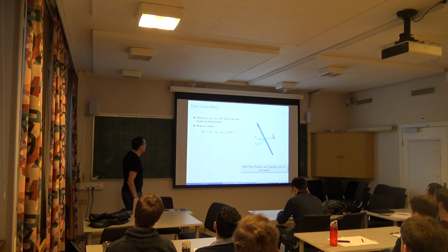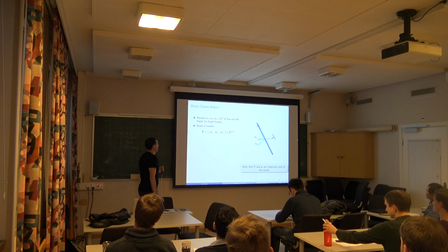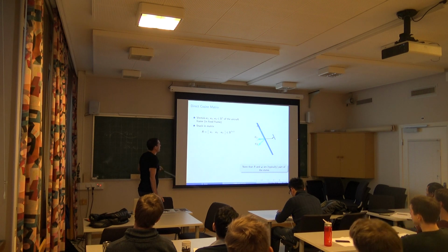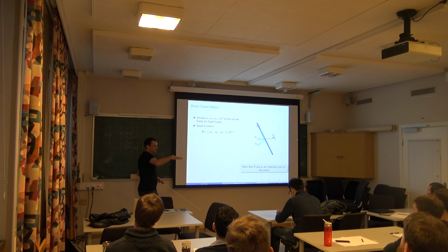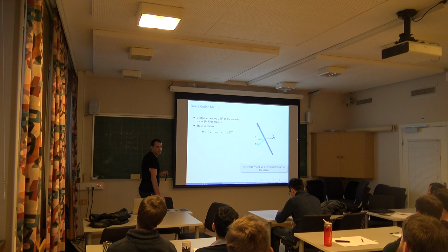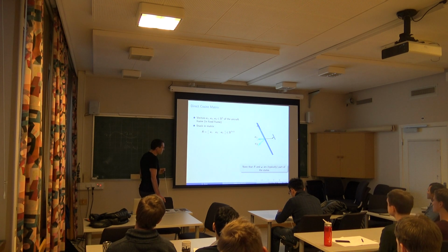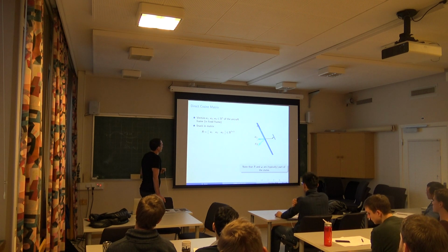Anyway, for example, if you want to represent the orientation of an aircraft, one way to do that, of course, is you can use angles, like the 3 rotation angles, and the rotation group has 3 degrees of freedom, so you can in principle do that. Does everyone know about singularities in the Euler angles? Yeah, okay, that's known. So most often, if you want to be safe in this context, you want to use either quaternions or the rotation matrices directly.